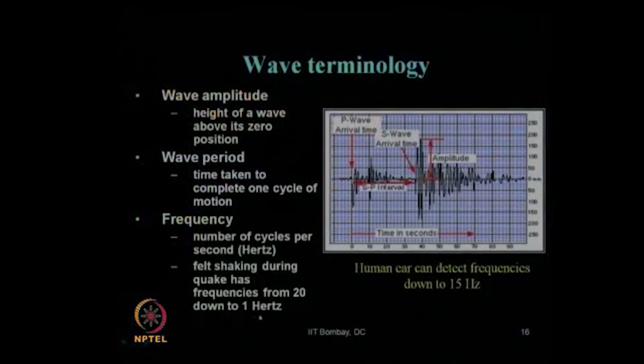As far as earthquakes are concerned, you can see it is between 1 hertz and 20 hertz, and mostly the shallow earthquakes which commonly cause the major destruction have frequencies between 1 and 3.5 or 4 hertz.